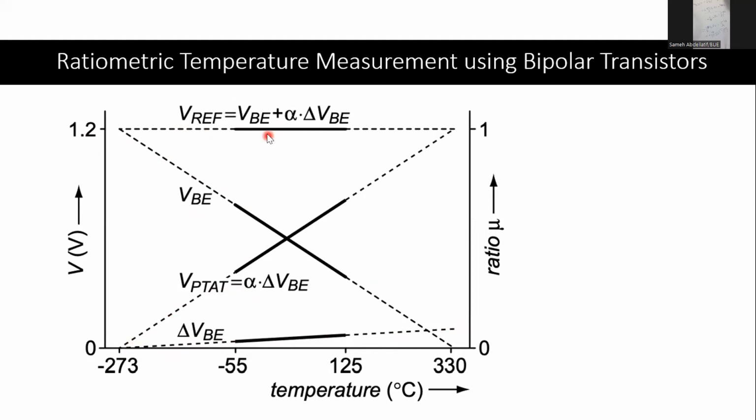And this is a very important concept in electronics. In order to create a voltage which is temperature independent, what you simply do is combine two voltages, each of them temperature dependent with an alternating or reverse polarity. So if your VPE against temperature takes this negative trend, you have now a compensating positive trend, so that you get this reference voltage as a temperature independent value.